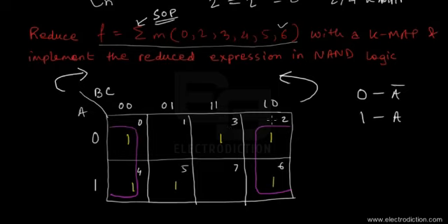They won't be alone because, I'll choose a different color in this case, we'll have the cells 2 and 3 grouping up together. And then, I'll take green, we'll have the cells 4 and 5 also grouping up together to form a pair. So we have the cells 2 and 3 on one hand, and on the other we have the cells 4 and 5 forming pairs. So we got 2 pairs and 1 quad.